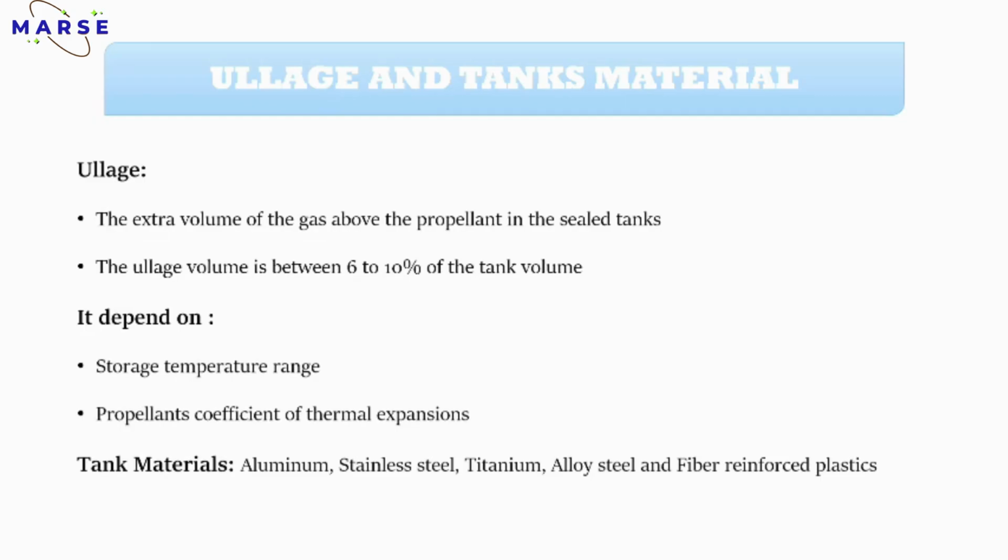Now the next one is the ullage part. What is meant by ullage? In the second slide we discussed the ullage. Ullage means some quantity of pressurized gas is present in the tank, not empty, but empty space in the tank. The extra volume of the gas above the propellant in the sealed tank. The ullage volume is between 6 to 10% of the tank volume.